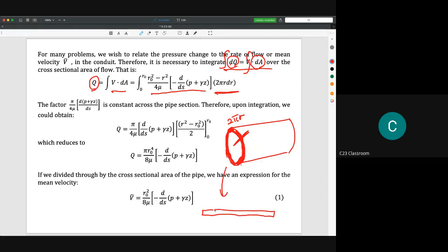like this. The length of this strip can be assumed as 2 pi r, and the difference in height is dr, because we are cutting at this point. That's why we use 2 pi r dr. If you read these notes, I think you can imagine it. We factor it like this, and finally we get this amount of flow rate. This is the total flow rate for that situation, and then we divide again by its